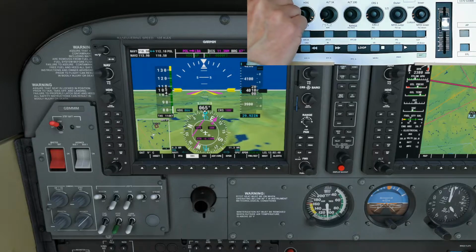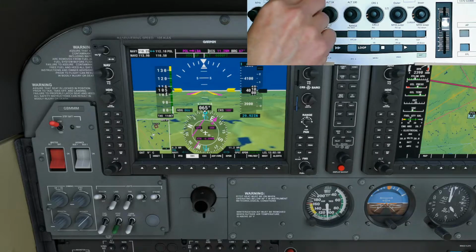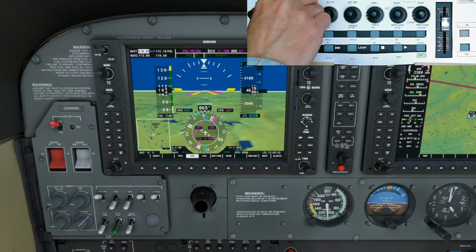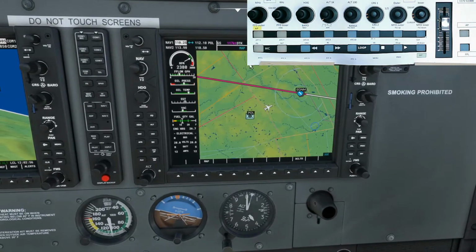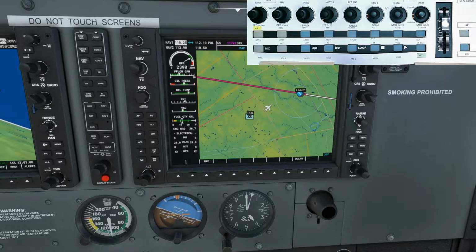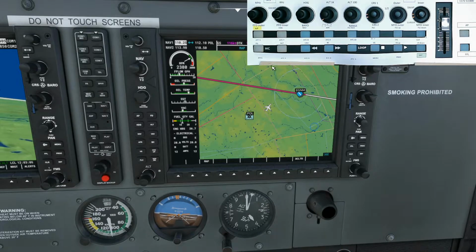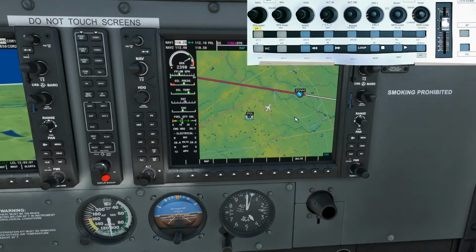It takes a bit of time, this. So I'm going to fly up towards the north. So I'm going to change my heading bug to the north. I'm going to change this to the runway heading, pick up that using the GPS and fly the runway heading.